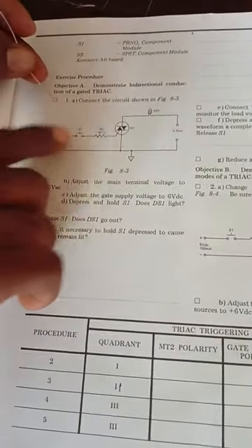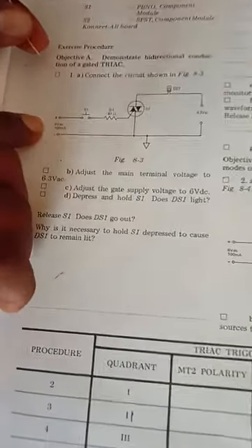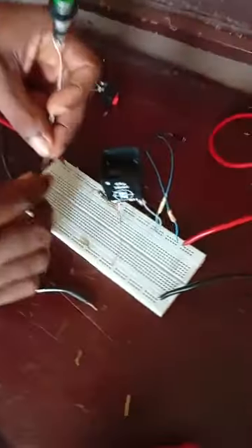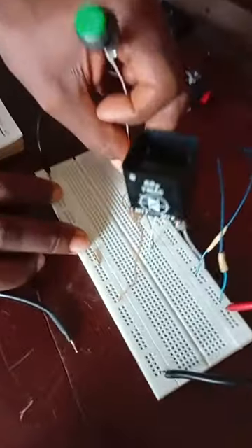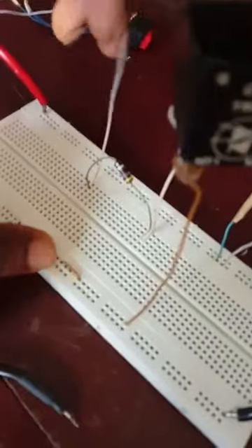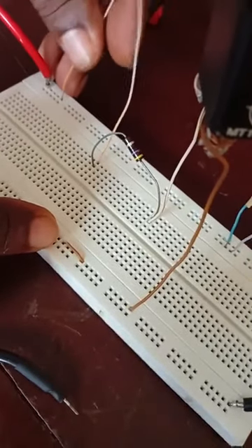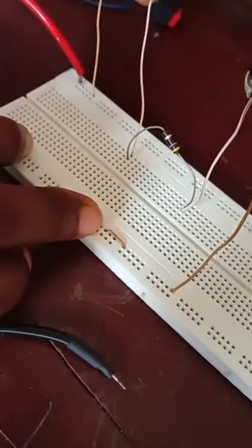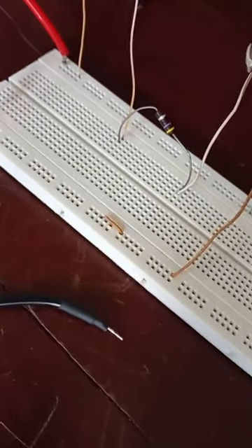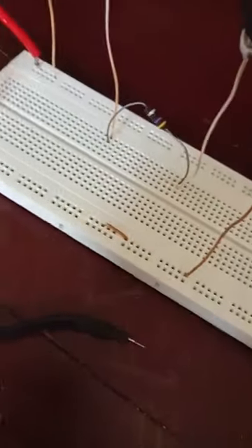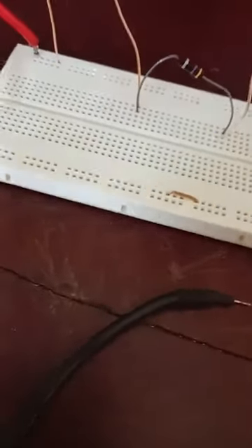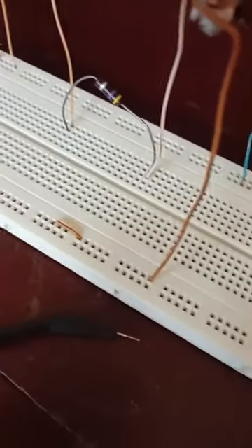So now if we look at the 47 ohm resistor, we need a press button. One terminal connected to the resistor, the other one to the positive of the DC source. Let's do that. This is our press button, normally open. So let's connect it. We have connected one hand to the resistor and the other leg of it to the positive of the DC source. So this circuit diagram is what we just did.